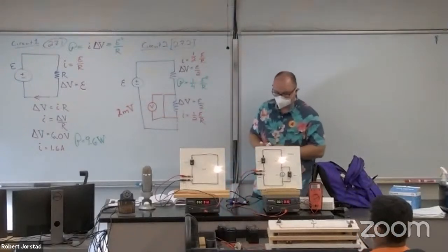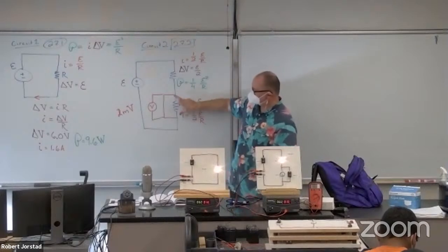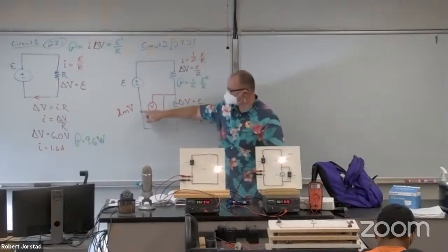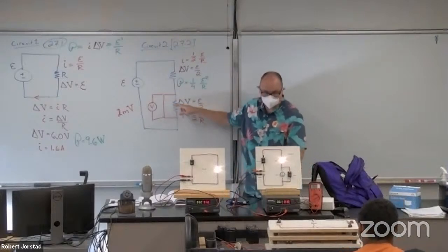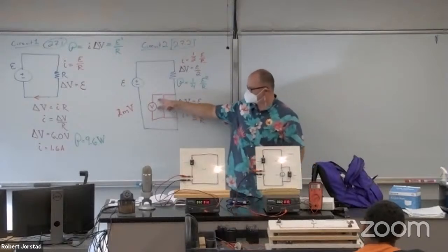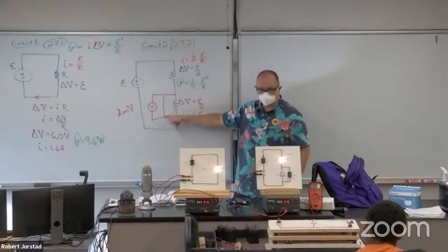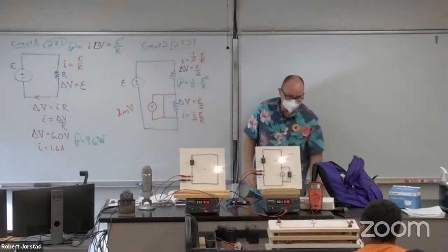To be clear, when I drop that switch, there's still a voltage across this. But it's so small, right? When I put that in parallel with this, these things in parallel share the same voltage. So if it's 2 millivolts across the switch itself, I can only get 2 millivolts across the bulb. That's not enough for it to light up.